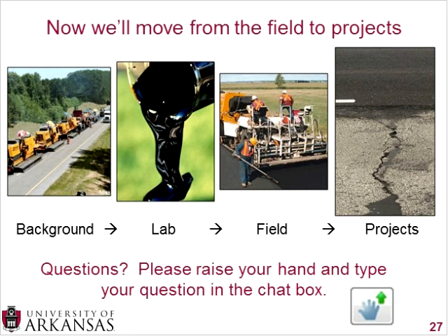And I love being able to answer this way, but there's no recommendation one way or the other. But I think what you would want to do is take samples from the field and then go through that mix design process and focus on the performance testing, because that'll really differentiate if the material that's in place will be able to be utilized in a future HIR design. And if you get very poor performance test numbers, then I would say it may not be a good idea to use HIR in this case, and you may want to do a more traditional mill and fill, which is where you take material away that's bad and then you put new material in.